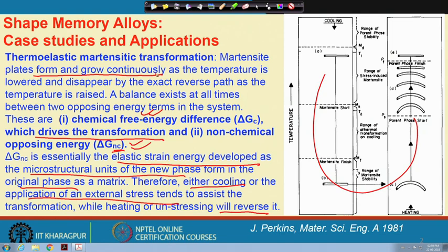Burst means all of a sudden the martensite forms, without showing typical nucleation and growth type features. So, a burst kind of formation of martensite is a common feature of the non thermoelastic nature of the martensite. But in some shape memory alloy systems, it has been observed that non thermoelastic martensite could also play a vital role and give some percentage of shape recovery.